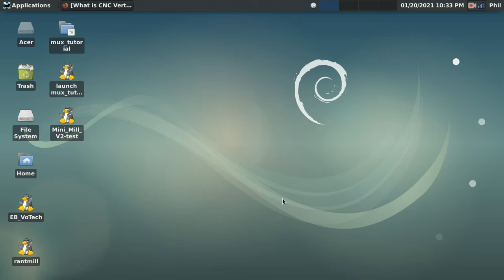because there's going to be a lot of back and forth between using the GUI environment to move the machine around, as well as the configuration environments that we're going to be getting into, such as the configuration wizards, the HAL files, which allow us to do crazy customizations and things like that, as well as the PLC environment that we're going to be getting into when we set up the tool setters, and if we wanted to build a machine with an ATC, an automatic tool changer.